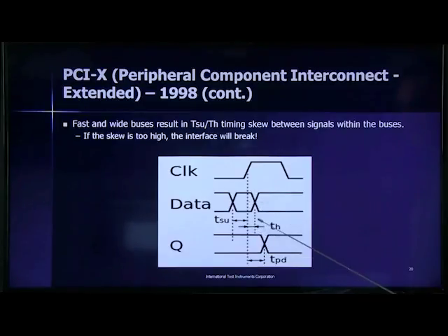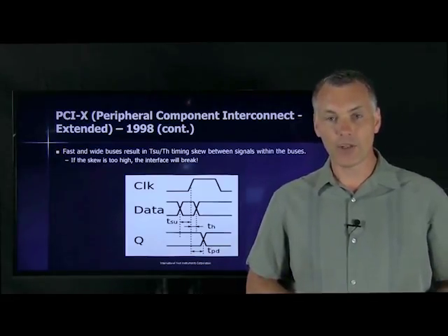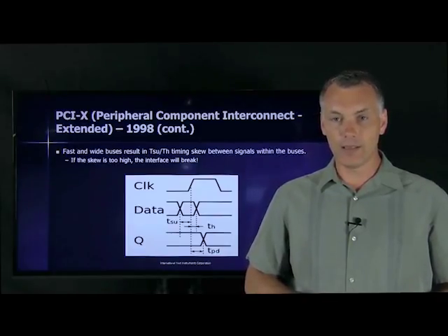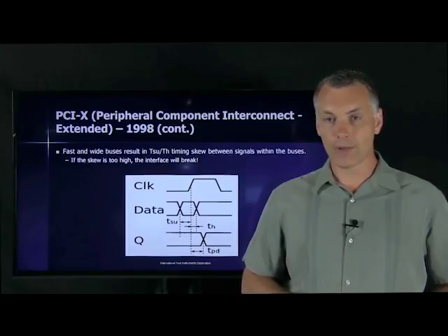If you have too little setup time, too little hold time, then you will end up with a situation called metastability, and that essentially means that you don't get the logic level that you expect, and it might be random. It might actually change after some nanoseconds. Chaos will surely ensue.